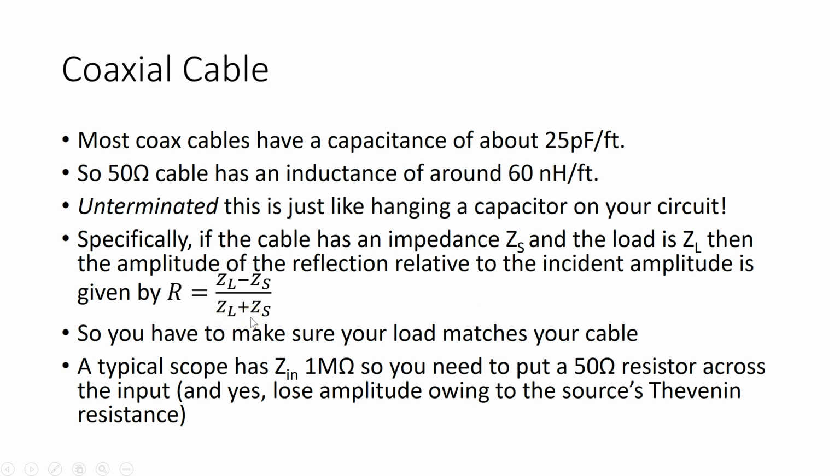So consistent with what we were talking about source and load impedances matching each other, if ZL equals ZS, the reflection coefficient is 0 and all the power in the cable is transmitted to the load without any of it being reflected back. Why am I telling you all this?